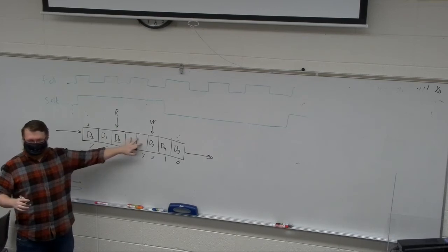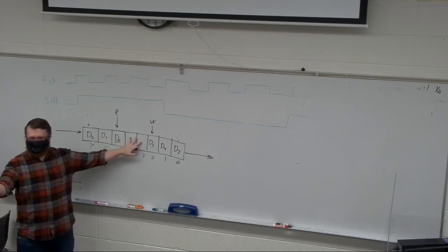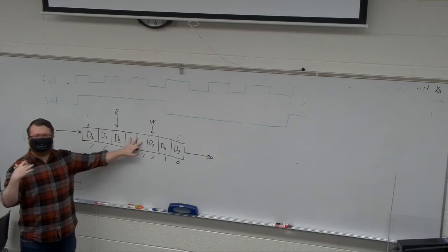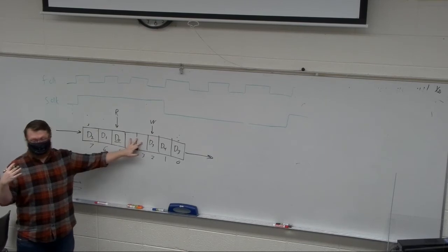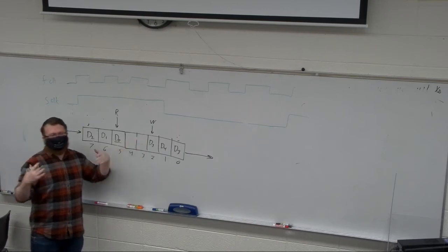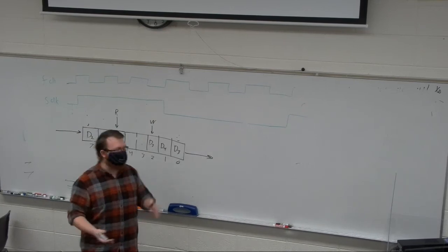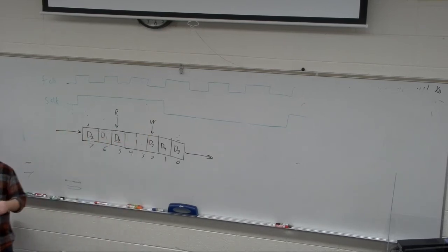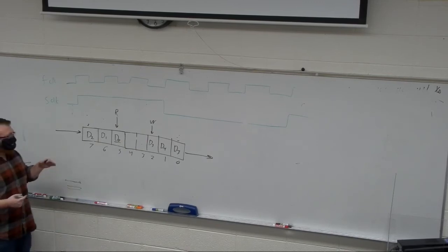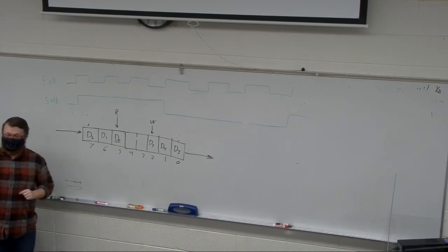And that could be an issue. This could be either direction in the data stream. It could be coming backwards and saying, I need you to stop writing to me, like soon. Or it could be pushing it forward and saying, I need you to start reading out or I'm going to run out of room. And you could have a situation where you're prioritizing different tasks and you would use that almost full as a prioritization flag saying this needs to happen now.